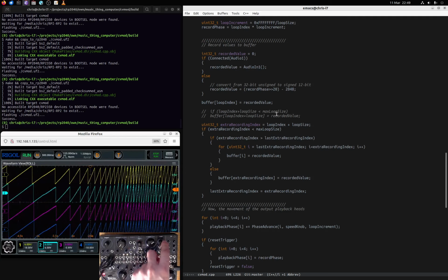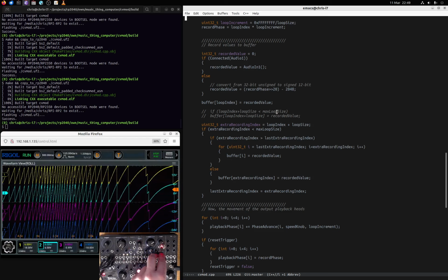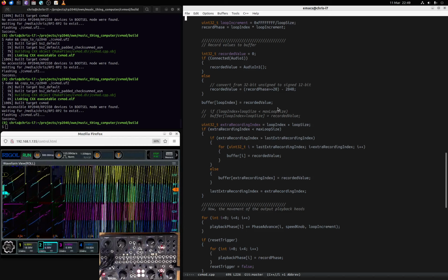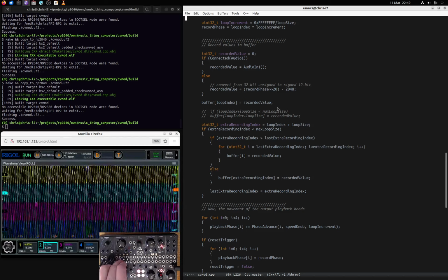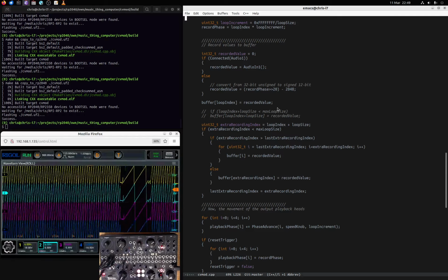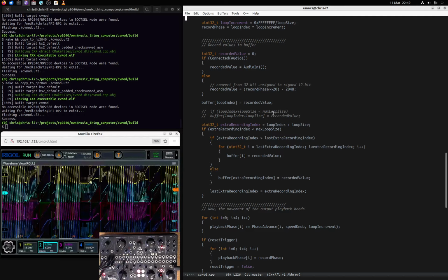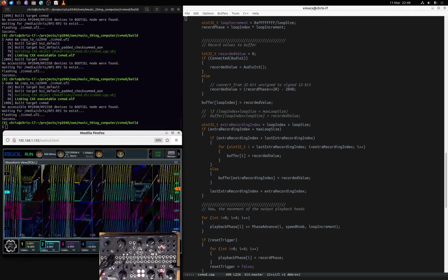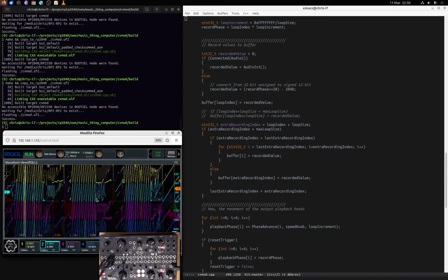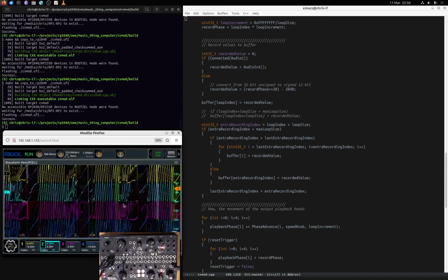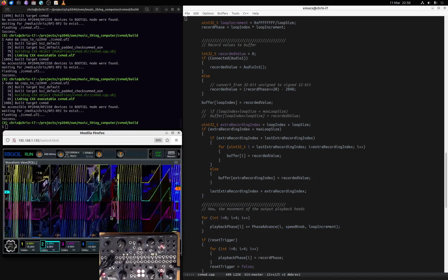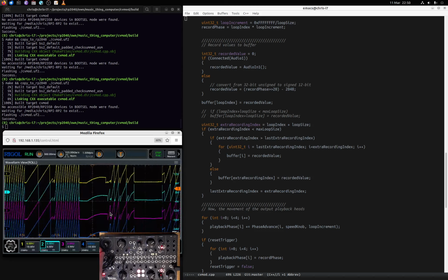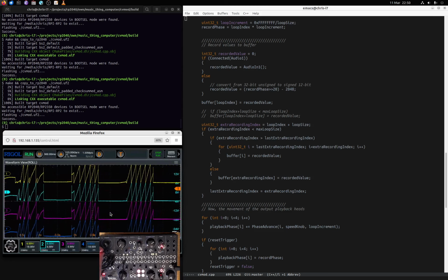So if we go from a slow LFO here and we actually go to a square wave, that's the worst case scenario. So a square wave works okay. Gosh, this is very glitchy scope, but it's okay. But that's because we are looking at a very short buffer length. But if I increase the buffer length, so we're actually jumping quite large amounts, what's that going to do?